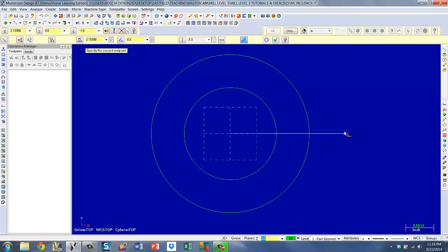And this is, remember, 0 degrees, 90. So I need one at 35 degrees off of the 90, which would put me at 55 degrees. So there's 55 degrees. When I hit enter, it'll place it, and then it just wants me to put an ending on it. Apply that.